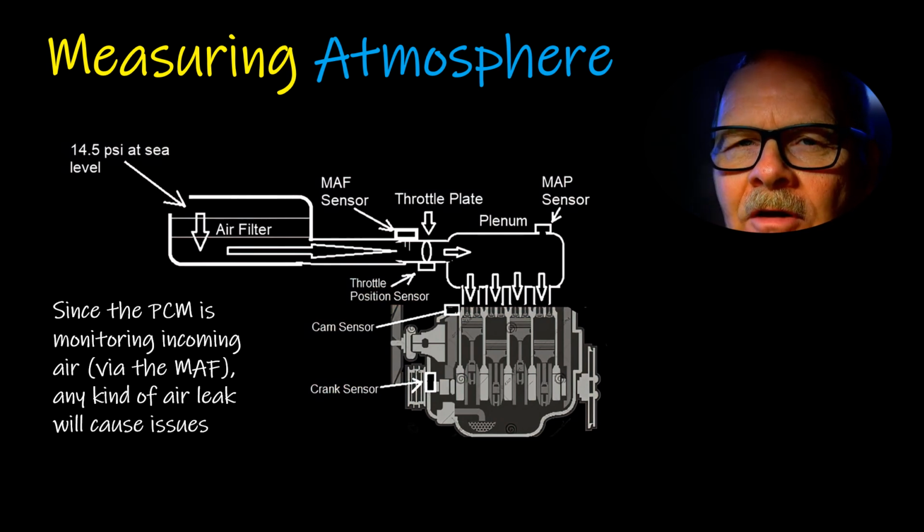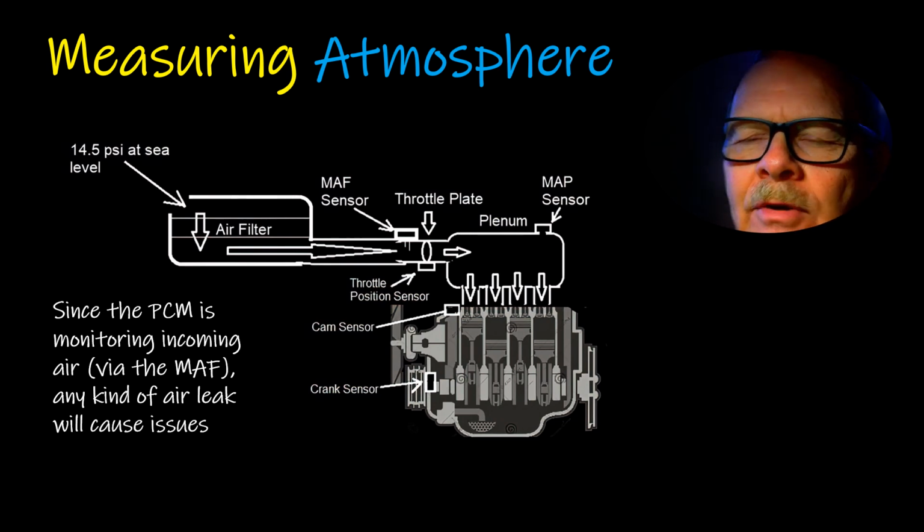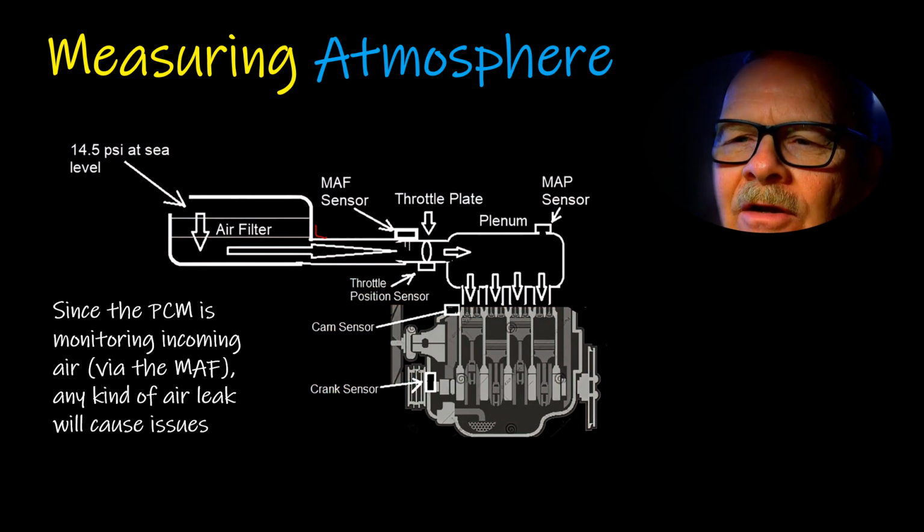If it doesn't, it'll cause problems. So they actually put the mass airflow sensor usually now out here instead of right there at the throttle body like it was on a lot of vehicles. And the PCV closure hose will be pulling its air out of this because it's clean air anyway.